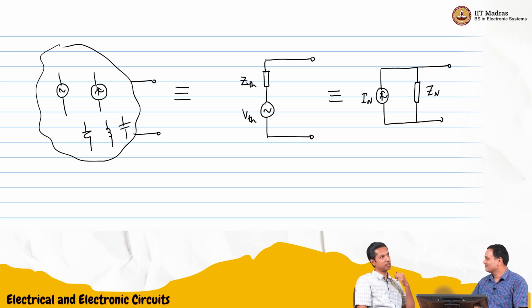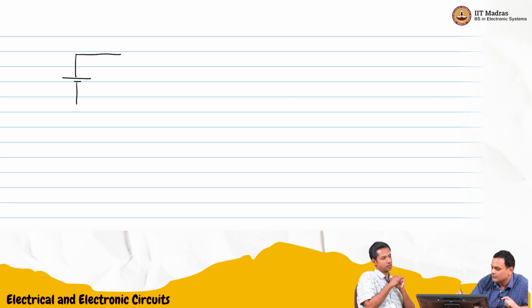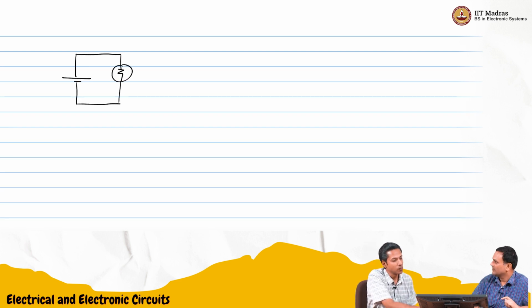So sometimes we use this 1.5 volt battery. If I just measure it like that, it gives 1.5. But if I connect a bulb or something and start drawing current, and then if I measure voltage across that load, usually it is lower than 1.5. That is true. So I'll show a bulb like this, right?